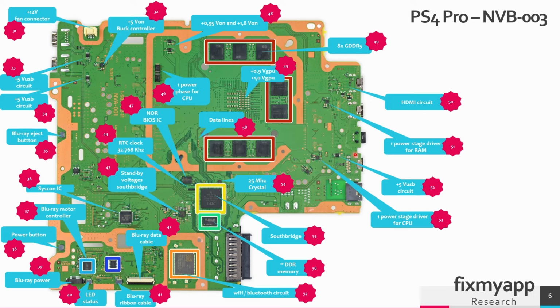This is a USB connector, and this USB connector will provide plus 5 volt USB, and this comes from this MOSFET. So when you press your power button, 5 volt power on will be generated. It will go to this MOSFET. This MOSFET will turn on, and then it's called 5 volt USB.